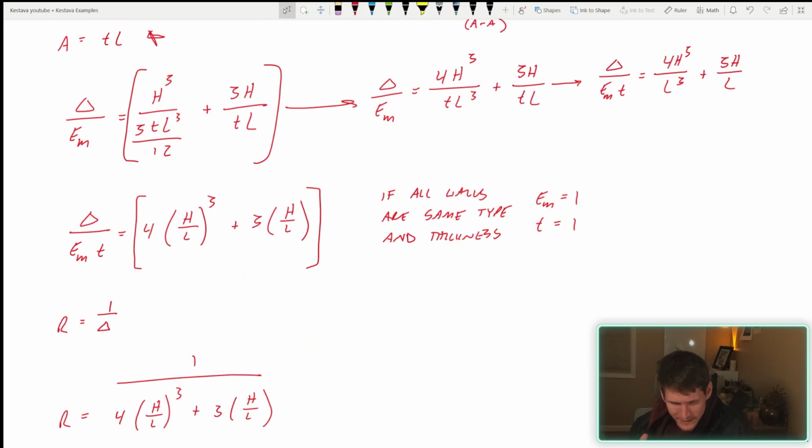Next, a big variable, or really a ratio, for our shear walls. The height of your shear wall and the length of your shear wall is very critical and drives a lot of the calculations for altering the stiffness of your shear walls. So we're going to keep that ratio within the parentheses, and pull out the other values just so it's pretty clear, as you start to mess around with your shear wall, how it affects the performance of the wall. So H over L we're going to throw into parentheses.